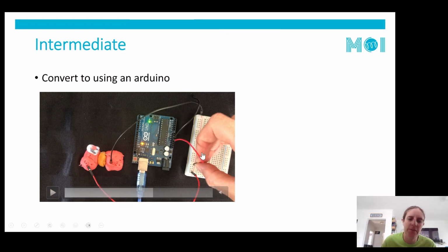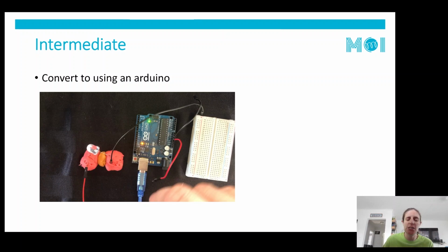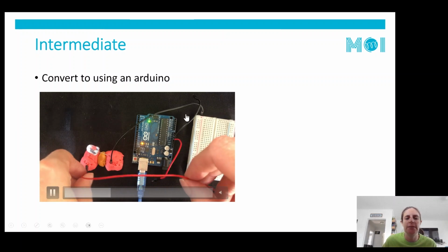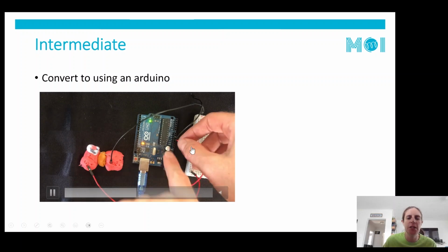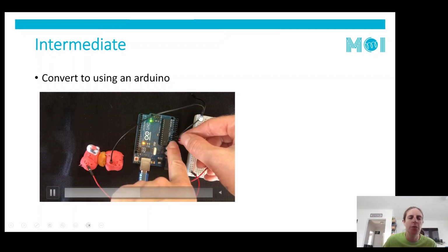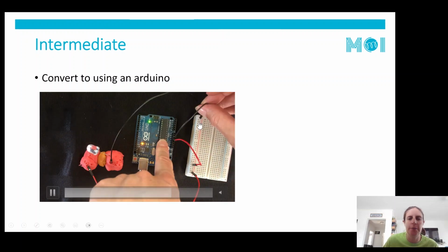So we're going to go from 5 volts into that power line again, our positive side, just like we did with our just converting to a normal breadboard. Then what we've got is here, there's one that says GND. There is more than one GND. You can use either one, it's fine. We're going to take our GND cable and we're going to put that into our negative line, just like we did with our power cable before. So it's our GND coming into that negative line.